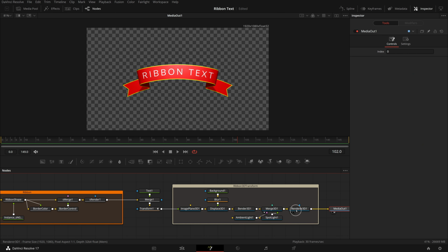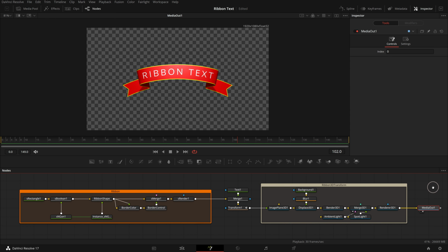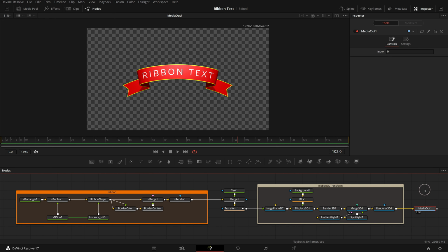But most of the time, we don't need a very complicated parameter structure for macros. Showing the parameters in a proper order usually is good enough. To control how the parameters will appear in the inspector, we can select the nodes in a certain order, so that parameters from the nodes will appear in the same order as the node selection.